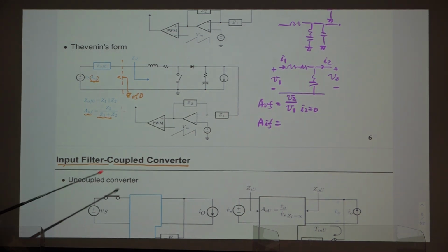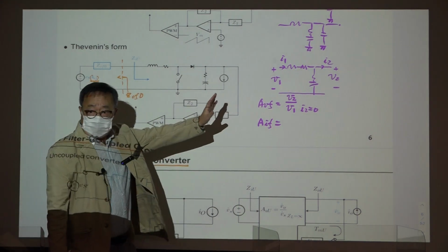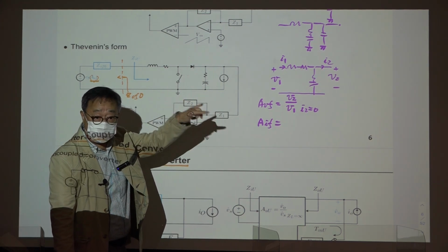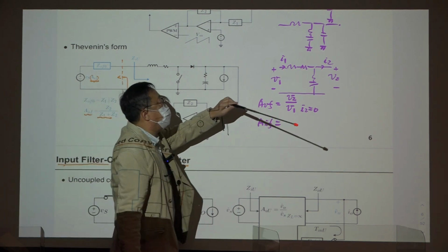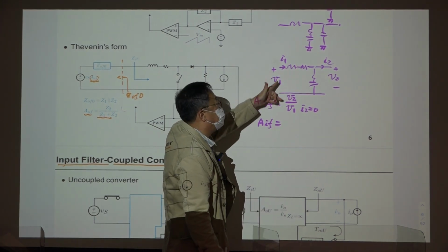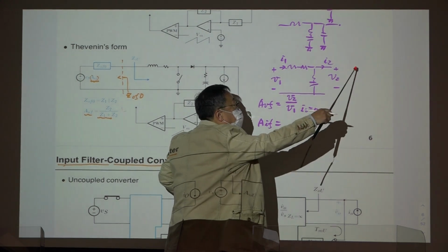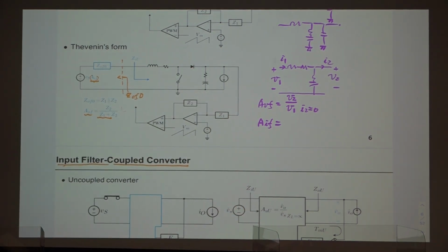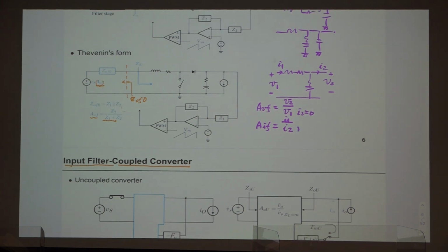And another very important attenuation is, this is our case. This current goes to the DC to DC converter. So there is a pulsating current, so it has DC component and AC component. What you want is DC component only coming from this port, and AC component circulating with this converter. For that purpose, we define current attenuation like this: I2, I1. I2 is input and I1 is output. And when evaluating this, V1 has to be 0.